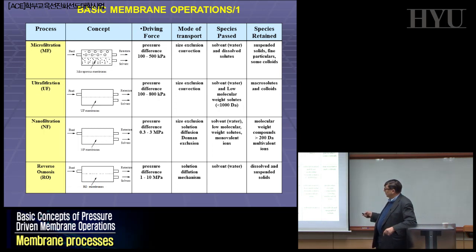In this case, water is going across, and some very low molecular species like sodium chloride or monovalent ions, but the bivalent ones don't go across. So if you want to separate bivalent ions, magnesium, calcium, strontium, barium, etc., from potassium, sodium, etc., nanofiltration is doing the job very nicely. That means you can have here a rejection of only 10–20% for sodium chloride that is going through. Magnesium chloride does not go through at all, and that is a big necessity at industrial level.